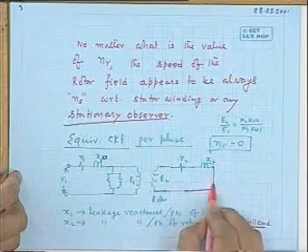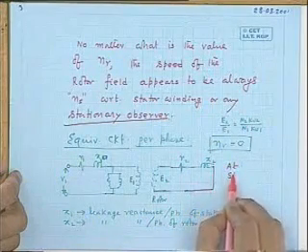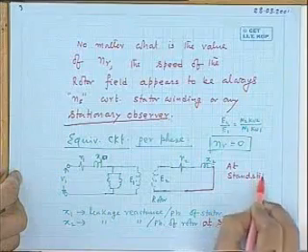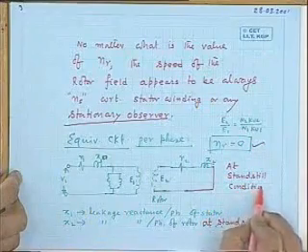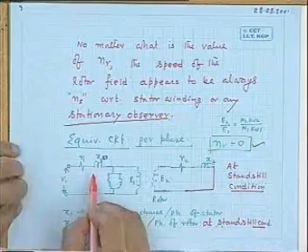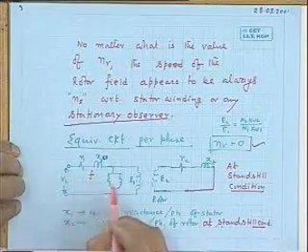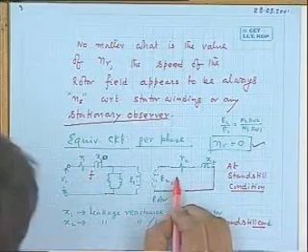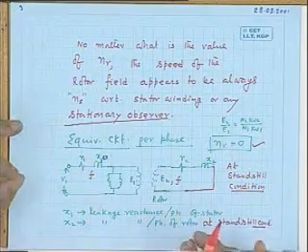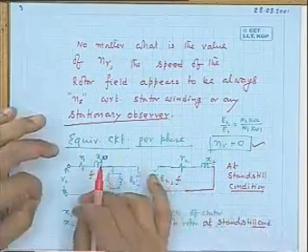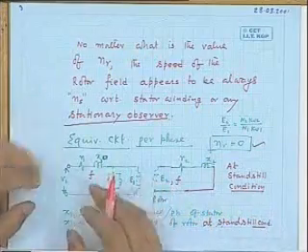So at standstill condition, NR equal to 0, the equivalent circuit is just like this. This will be the equivalent circuit. And what is the frequency of stator current? It is always F. What is the frequency of rotor current? I will write E2 and F here during standstill condition. So during standstill condition, the equivalent circuit referred to primary side is just like a transformer, no problem at all. This voltage frequency, this voltage frequency, frequencies are same.